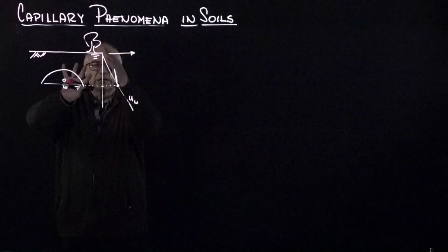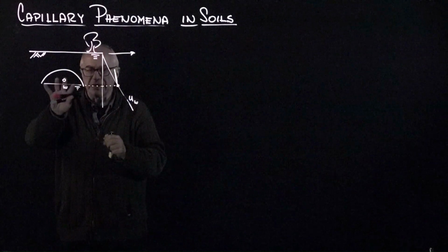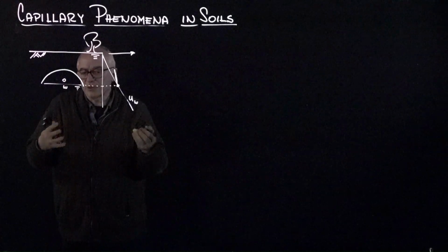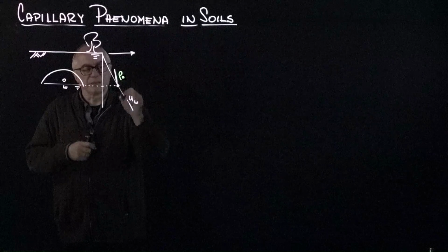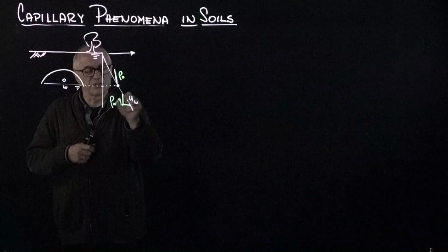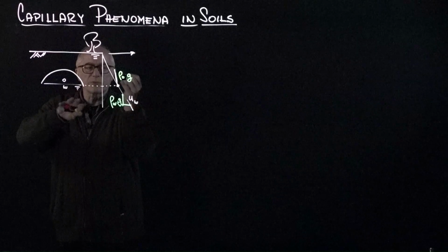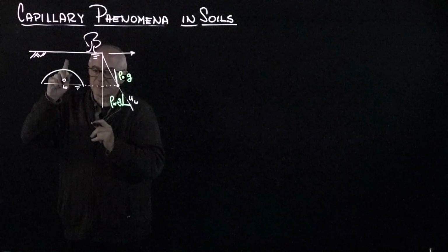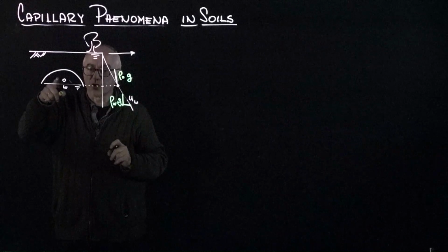Outside, the pressure of the water increases with depth. Inside, beneath the anticline, the pressure of the oil increases proportional to its unit weight. In other words, the mass density of oil times g, while here it follows the mass density of water times g. Therefore, now there is a difference between the water pressure and the oil pressure, even inside the anticline, because, as we showed before, this is not just filled with oil, it's filled with oil and water.